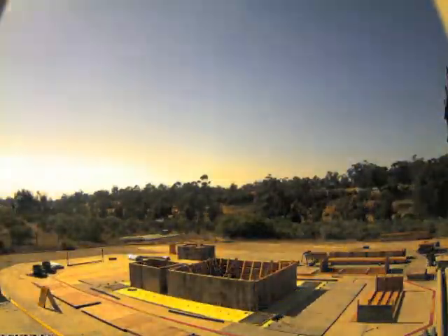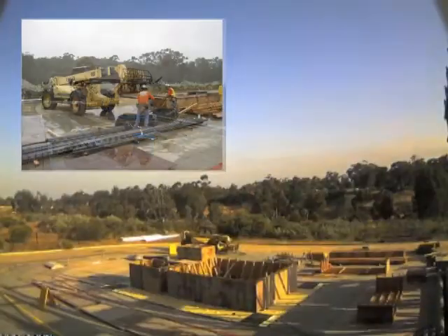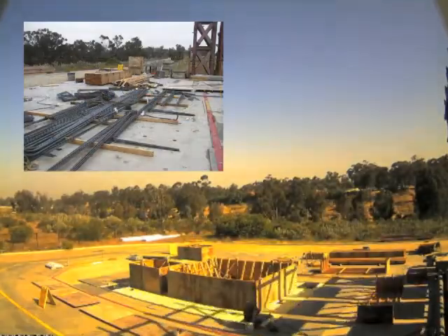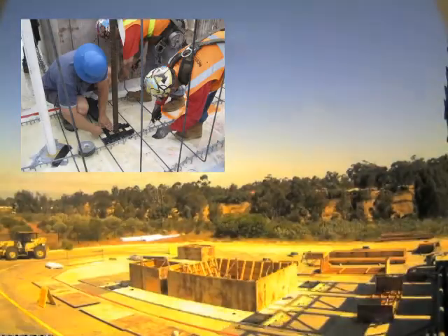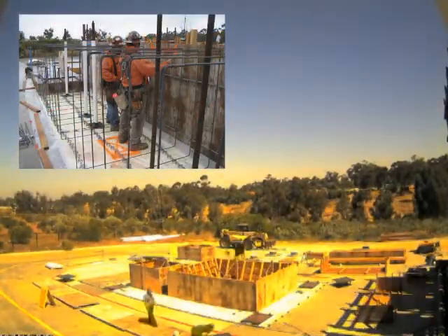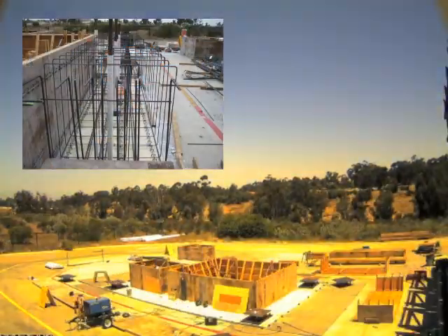After the construction of the foundation formwork is complete, steel reinforcing bars, simply termed rebar in the field, are installed. When a concrete section is reinforced with steel rebar, it is termed reinforced concrete. These carbon steel reinforcing bars, which are ribbed to facilitate a strong mechanical interlock with the concrete, are used to increase the tensile strength of concrete, since it is weak in tension.